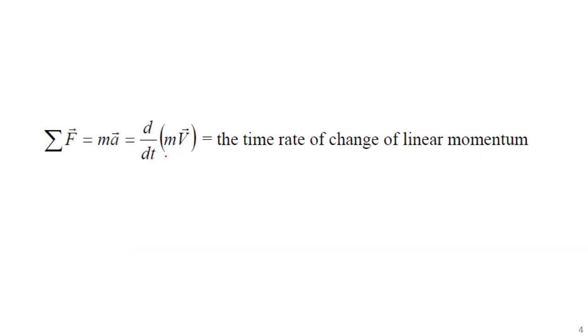And we can look at mass times acceleration as the time rate of change of linear momentum, which is kind of convenient. So basically, this sum of the forces would be the pressures acting all over the surfaces. It would be the weight. Those are known as body forces. Ma is the mass times acceleration of the little cube, dx, dy, dz.